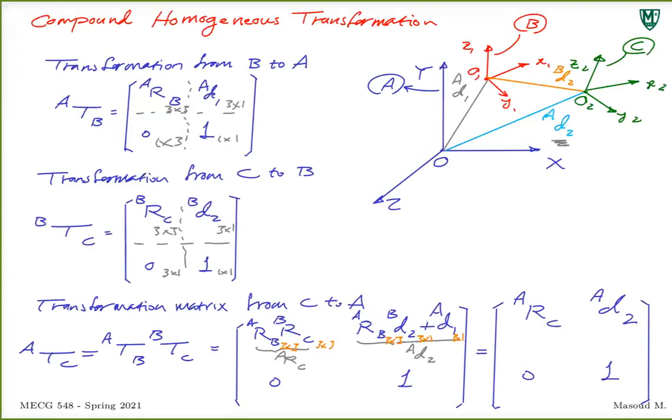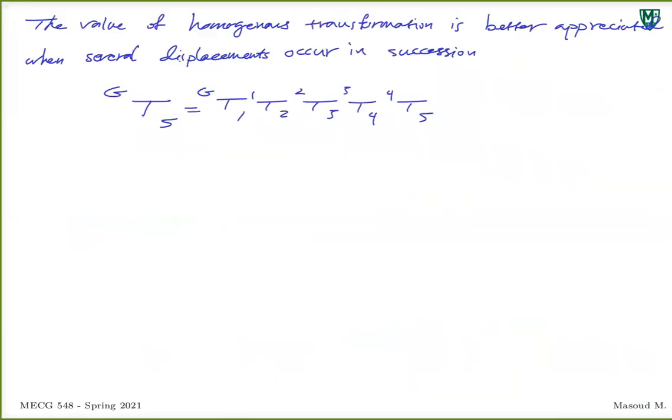We were talking about compound homogeneous transformation. The story is basically that we are transforming coordinates between multiple frames, not just two frames. What do we do? We just go with pairs of frames. For every two frames, we find a transformation matrix between those two, and from there the story is just matrix multiplication. Just as always, we end up doing math.